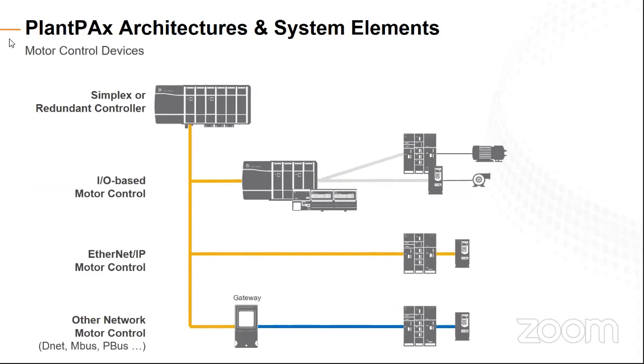And the last piece here is the power side of it. Obviously, if we're talking about Modbus connections or anything else, those would come in just as standard I/O. But if we're doing tie-ins, anything that is an EtherNet/IP device from us, whether it's a PowerFlex 755 or 525, those are fair game. Those look like I/O to us. It's the same way that a static switch looks to us. And anything else will just require some type of gateway system. So the MCCs, all that power lineup side is also I/O when we look at the PlantPAx system.